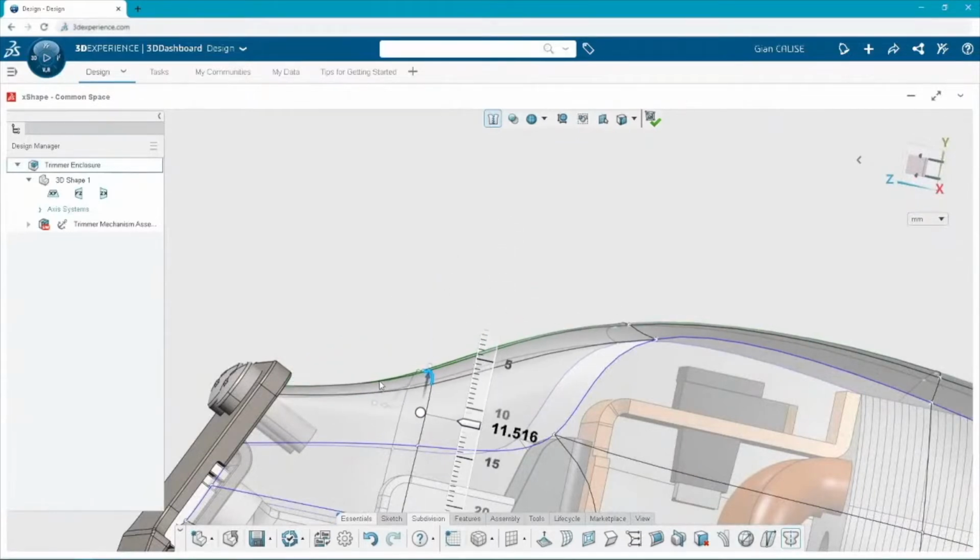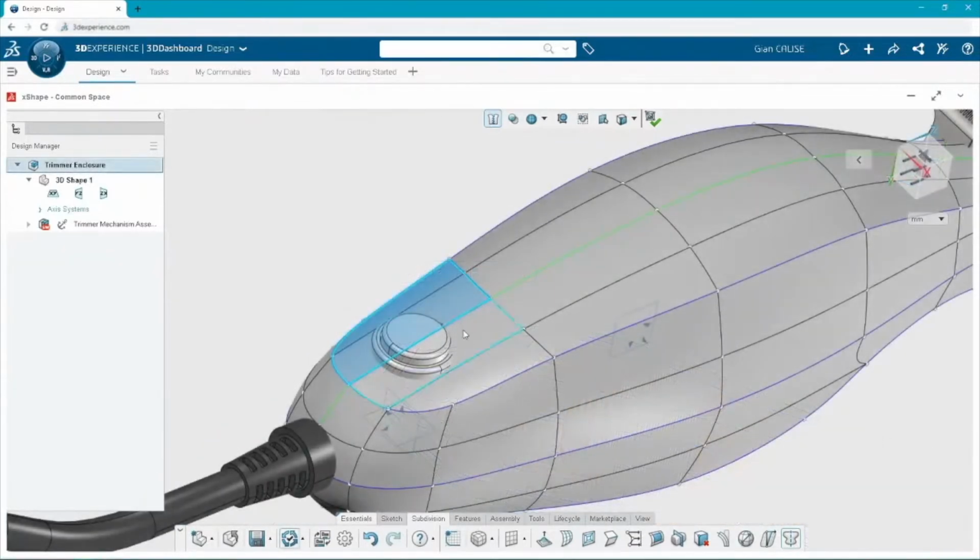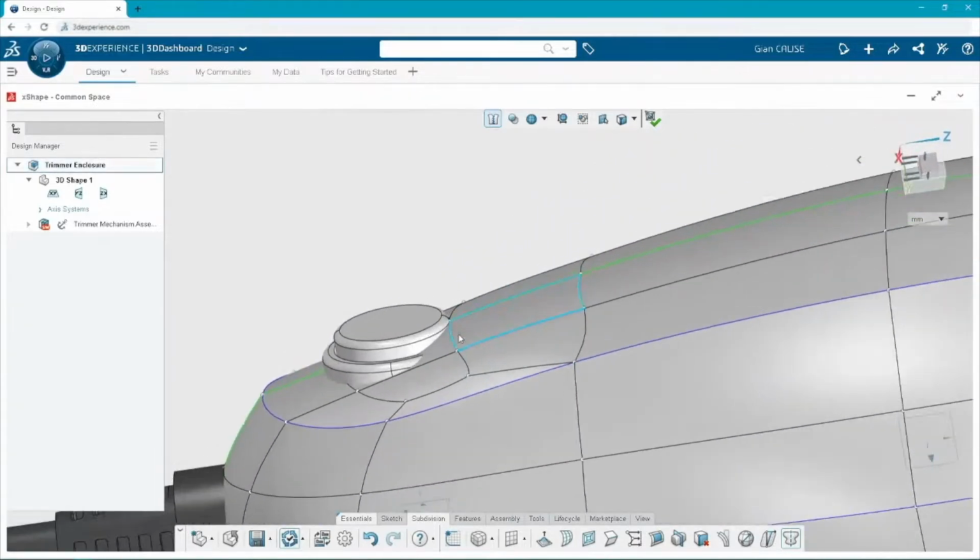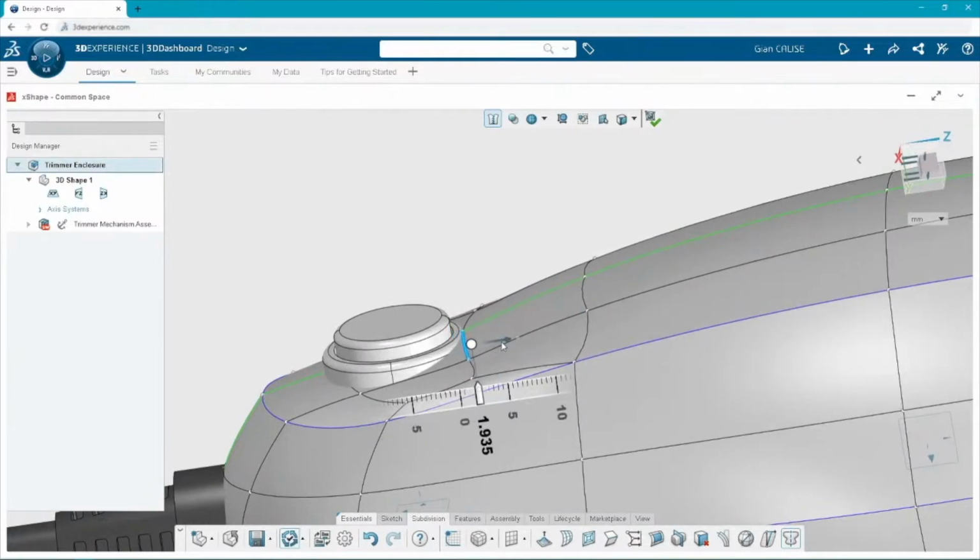Now, the next thing I want to show you is how you can get more localized control over a certain area in the model, and that's using the subdivide feature. The subdivide feature just takes these four faces and will split them into a new number of faces. In this case, I think it's going to be about 14, but this is where the term subdivision modeling comes from. So it'll basically take an offset of the edges you selected and place those within. And then you can grab, control, push and pull those however you'd like to get that shape that you're looking for.